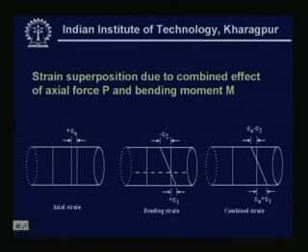So, looking from that aspect, just by putting an axial load, we are having an axial strain epsilon A. And if it is having a bending, you can see the bending here is compressive, here is tensile. That means you are applying a bending moment in such a way that, looking from this side, here is clockwise and here is anti-clockwise. Now, what is the imposed effect?